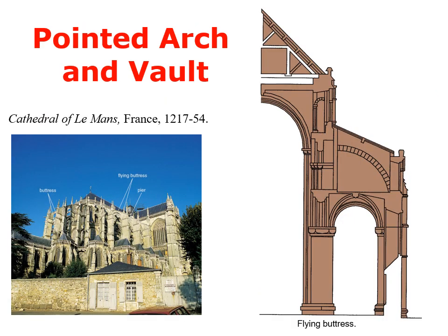And so on the outside of these massive churches, there are some other architectural terminologies and things to understand. As you build higher, you have to support the walls. So you have buttressing. Buttressing is basically like a little perpendicular wall that you put up against an exterior wall, and it helps to transfer the weight as well as supporting the wall. The higher up you go, the bigger your buttresses need to be. But of course, if the buttresses are too big, then they don't allow any light to go through.